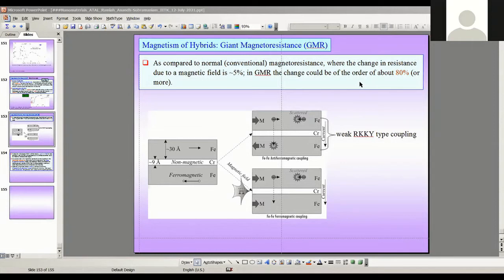how the inverse Hall-Petch relation happens. Okay, that's the next question perhaps. So what is the reason for the Hall-Petch effect? Normally people say it is the dislocation pileup at the grain boundary which leads to the Hall-Petch relation. But people are repeatedly now thinking that that is not true.